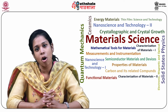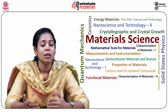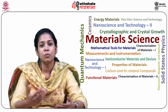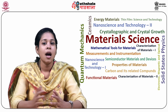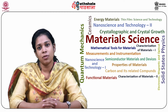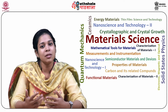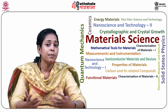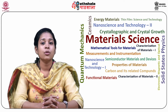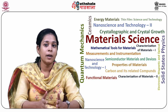The control of microstructure can overcome inherent stiffness to allow the production of ceramic springs and ceramic composites which have been produced with a fracture toughness about half that of steel. Also, the atomic structures are often of low symmetry, which gives some ceramics interesting electromechanical properties like piezoelectricity, which is used in sensors and transducers. So the structure of most ceramics varies from relatively simple to very complex.